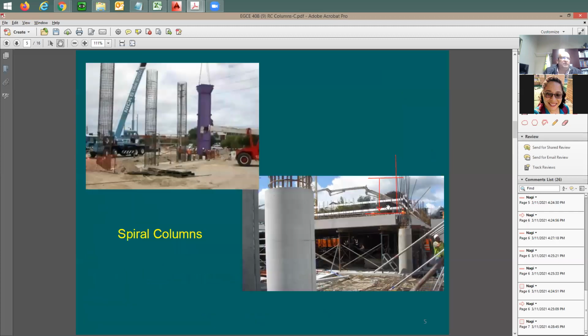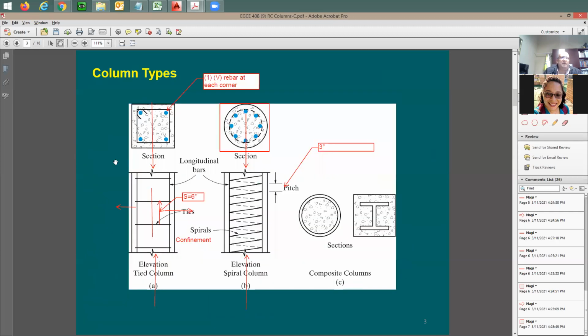Let me go back here to this column elevation, and now let's talk about this. Let's say you have the column here in plan, and this elevation. Our estimate is that the axial load is going to be right in the middle. But most likely this axial load is going to have some eccentricity, because no column is going to have only pure axial force.